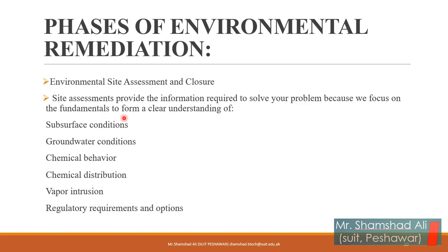Subsurface condition of that particular site, groundwater condition of that particular site, and if there is some kind of chemical, what kind of chemical, its behavior, chemical distribution, whether it is at the minimum, maximum, or in the normal range, vapor intrusion if required, and regulatory requirements and options.